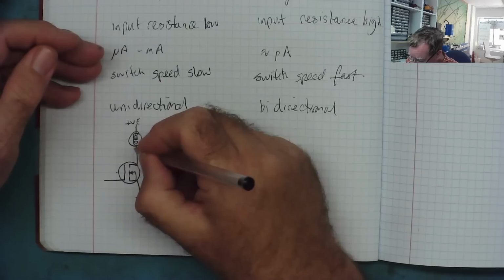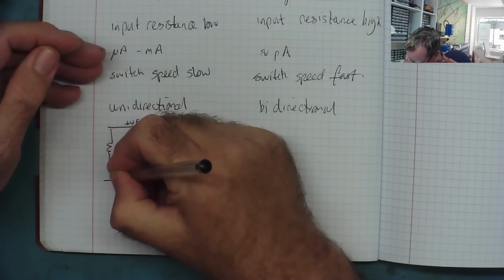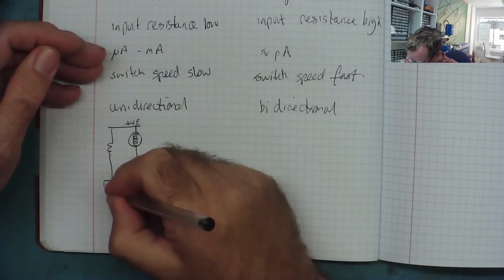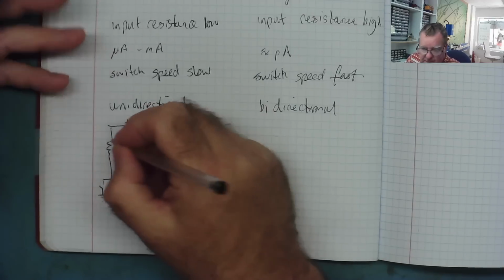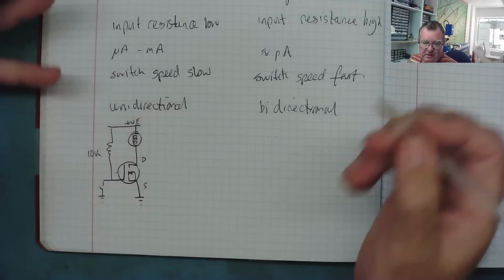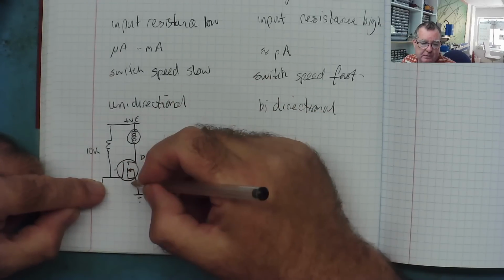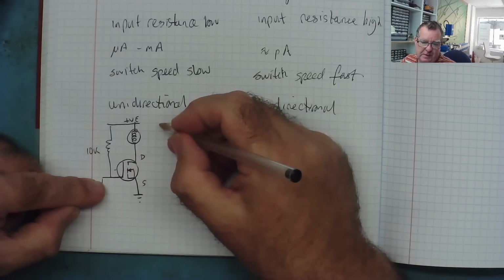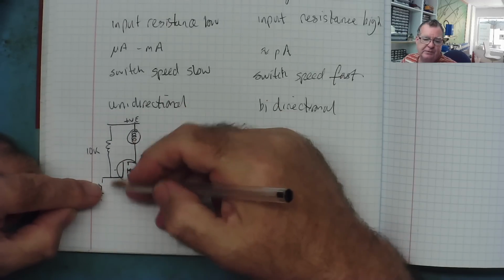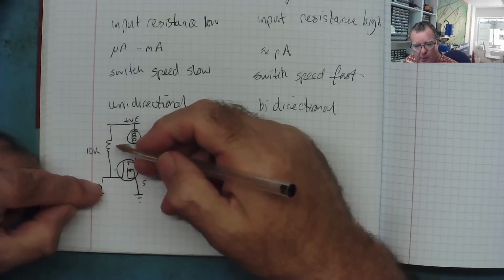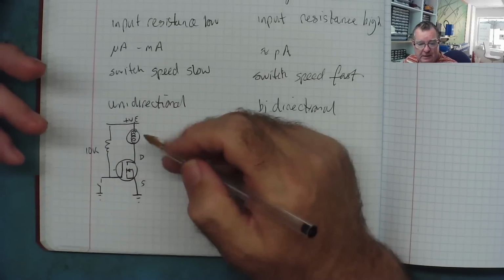It will turn on. So we can take, for example, from here a resistor to the positive supply, and we can take a switch to ground, and we can make this quite a high value resistor, 10k or something. So when we close the switch, we ground the gate and the thing switches off. When we open the switch, this resistor pulls the gate voltage high. It goes above 3 volts. In fact, it will go up to the supply voltage, and it switches on. And that's how it works.